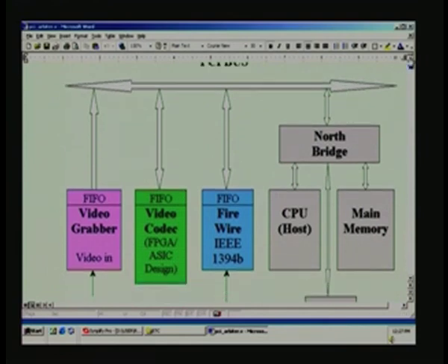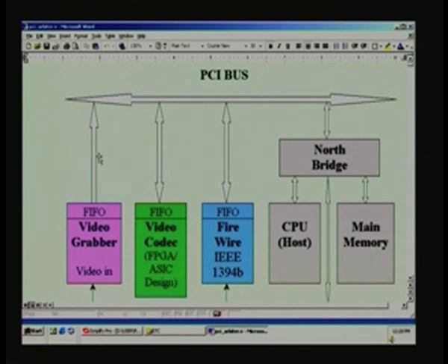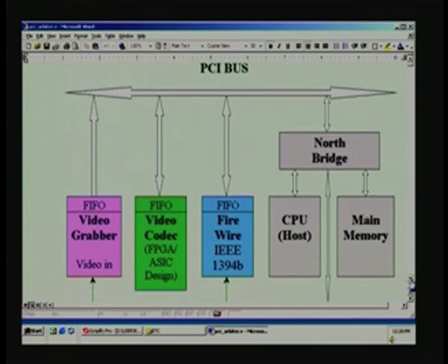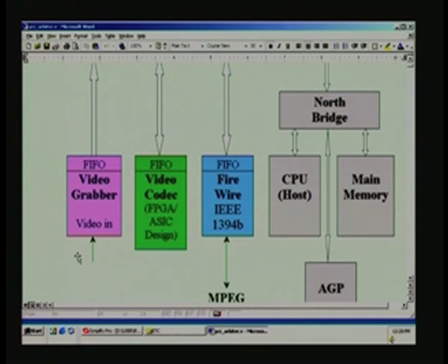So, this is for a video application. Right now what we have is a camera here, and that is basically a video coming in PAL, or it can be an NTSC sequence, and this is hardware to grab this video. It may even be a JPEG input, and another input can be a VCR or VCP, and there can also be another format such as XGA or SVGA entering straight away as a video. No matter what the video is, this video grabber collects this information.